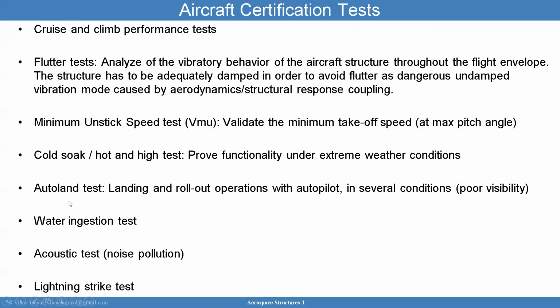An auto land test makes sure that the aircraft can survive poor visibility conditions like landing and rollout operations. You want to make sure you can do that with autopilot. You also have to do a water ingestion test because you could be flying through rain. We want to make sure the engine can do a good job there. Then there is acoustic testing, like noise pollution, and the lightning strike test. There are other tests too, like, for example, taking a blade and breaking it apart to see if it can survive,